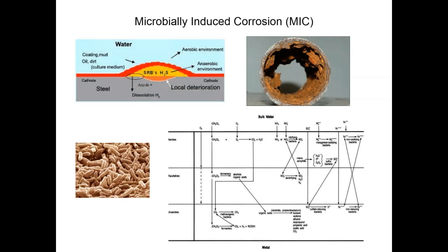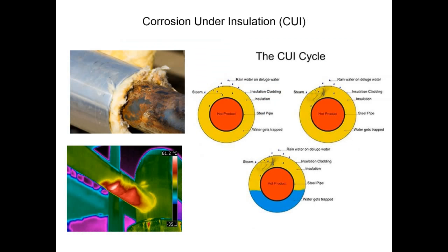It can be tested, different species are available, but one of the best ways to reduce them is to use biocides. Corrosion under insulation is a type of corrosion that's quite common, in that the environment under the insulation is not observed, obviously, but the geometry and the way the insulation can be penetrated as a barrier material can result in accumulation of moisture, water, or other corrosion species, resulting in a local concentration and hence unseen type of corrosion.